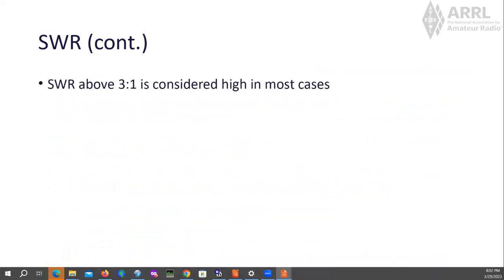And if you remember, they said that when an antenna has no impedance is when it's resonant. And an antenna can only have no impedance at one frequency. So an antenna that's set up to have perfect SWR in the middle of a ham band, anywhere else in the band, it won't have a perfect one-to-one SWR.